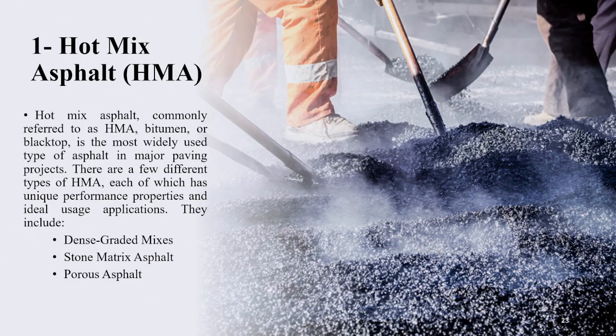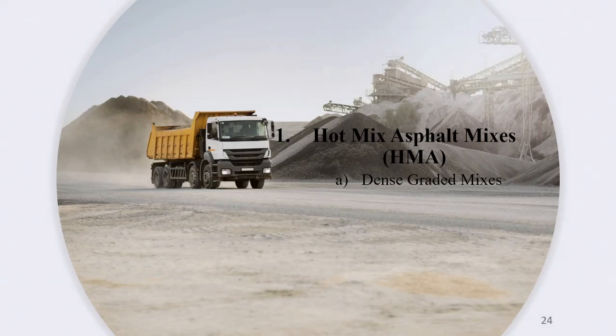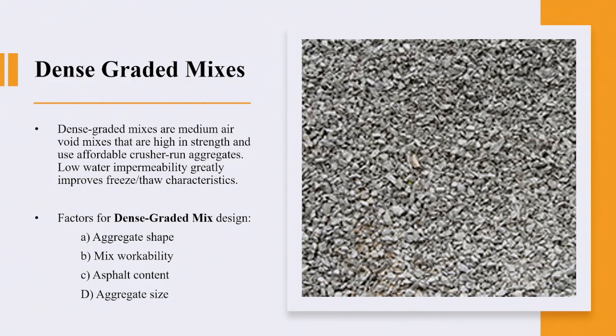Okay, so but probably you'd end up with a lot of rutting this way. You know, yeah, because right now even with dense graded we push more than 19, and with stone matrix we push up to 30 millimeter, or like 1.25 inches for the coarse aggregate, so that, you know, it's better for fighting the ruts.